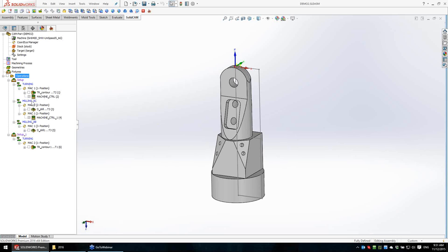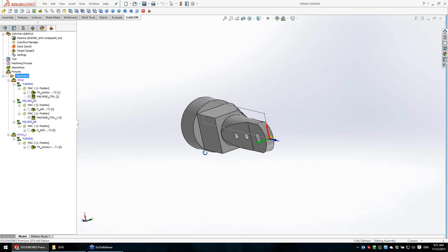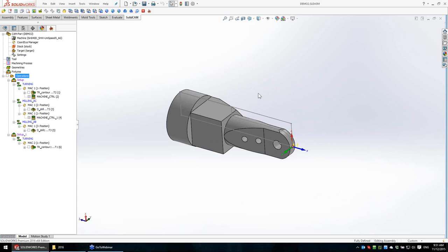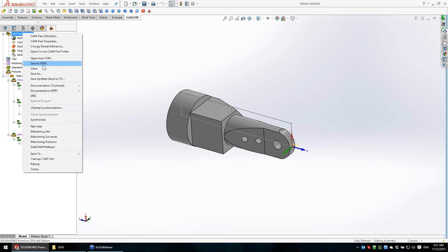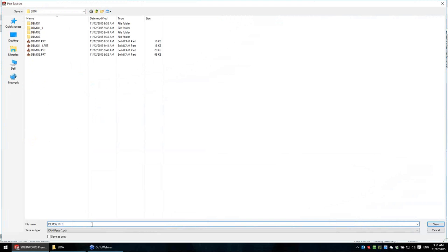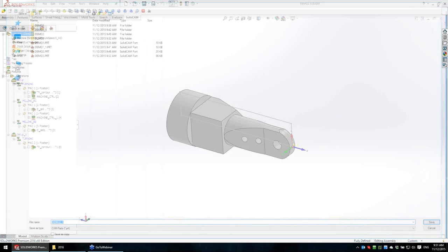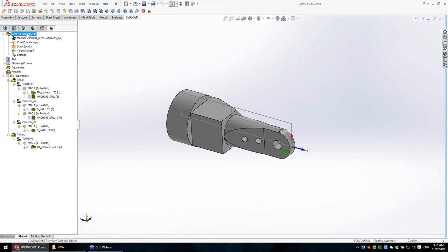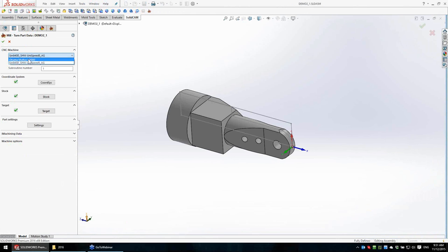Now let's try to move this part to another machine. We have here different kinematics, different sub-machines using MCO, the second setup. What happens if I move this part to a standard mill-turn machine, like a horizontal one, like an Okuma or Integrex with 2 tables? So let's first copy this part and see what happens, and change the machine. I select a new machine in the collection, Multus U3000,